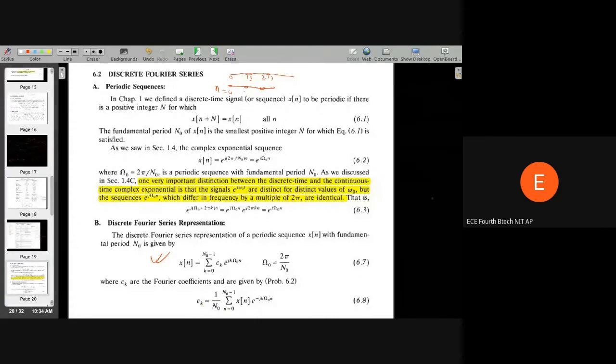You can use a discrete Fourier series, and these are the two relations. It's very similar to continuous Fourier series, as you can see, but there is no integration, because it's a discrete sequence of numbers. So again, this is nothing but an inner product of a sinusoid with the signal to get your coefficients. That's the concept.